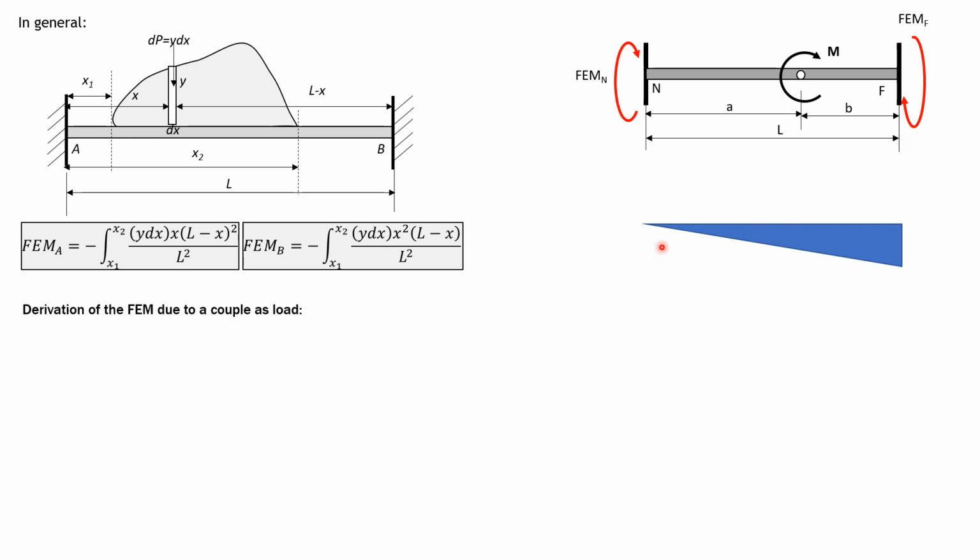So this is the moment due to the reaction at N. The reaction at N is expected to be downward because the moment is clockwise. For instance, if the supports are simply supported, reaction times L equals moment, right? So this is RnL over EI, or since EI is treated as one, you cannot affect with fixed moment, so RnL.